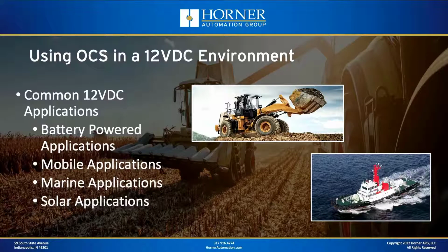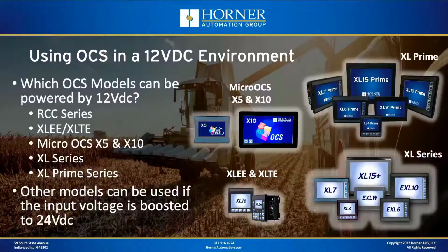For example, automotive applications, of course, are about as common a mobile application as you can come by. But with the advent and popularity of electric vehicles, there's a lot more 24 volts being used in the automobile these days than ever before. So it's not automatically a 12-volt application if it's automotive, for instance. So always check to see, in your particular case, what the voltage is before you proceed, of course.